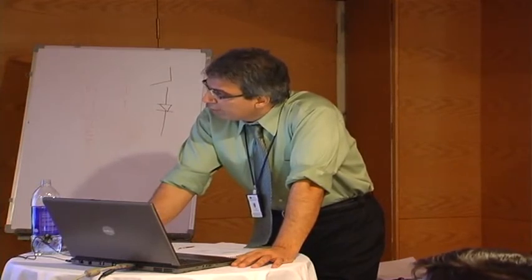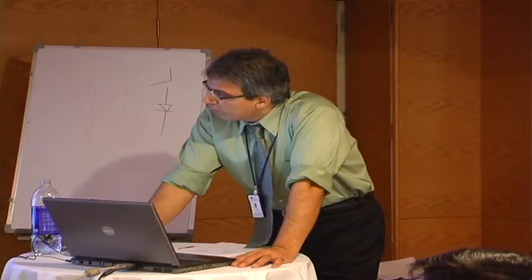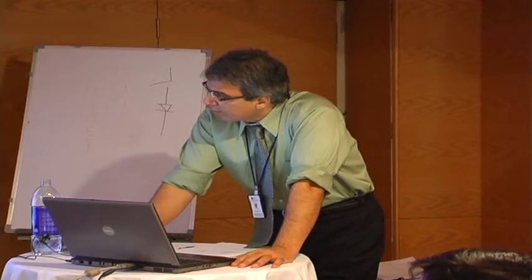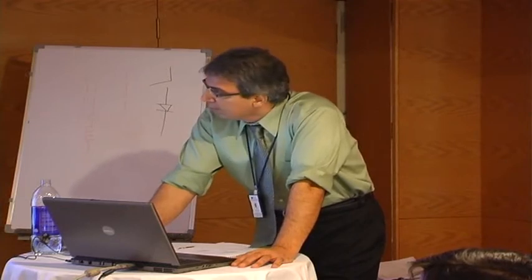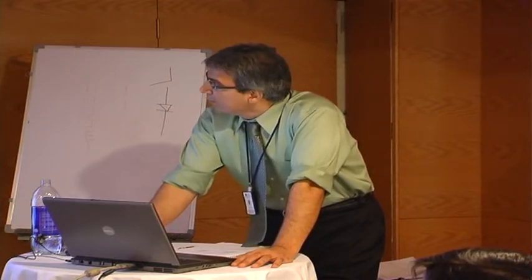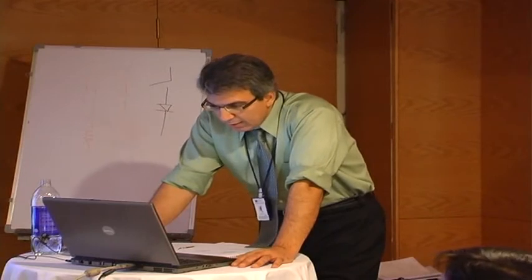And here you have got an E source, and the value is basically that same cosine function we had discussed. And then you have a second E source, which is based on a tan hyperbolic function, right? So that's your PWM.